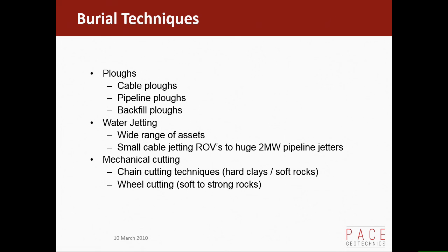I know this has got cable ploughs in it, so we're just going to concentrate on pipeline ploughs and backfill ploughs. You need a plough to cut the trench and another plough to backfill it. Water jet trenching, quite a number of assets out there, from quite small ROVs to 2 megawatt pipeline jetters, and 2 megawatts is a lot of power.